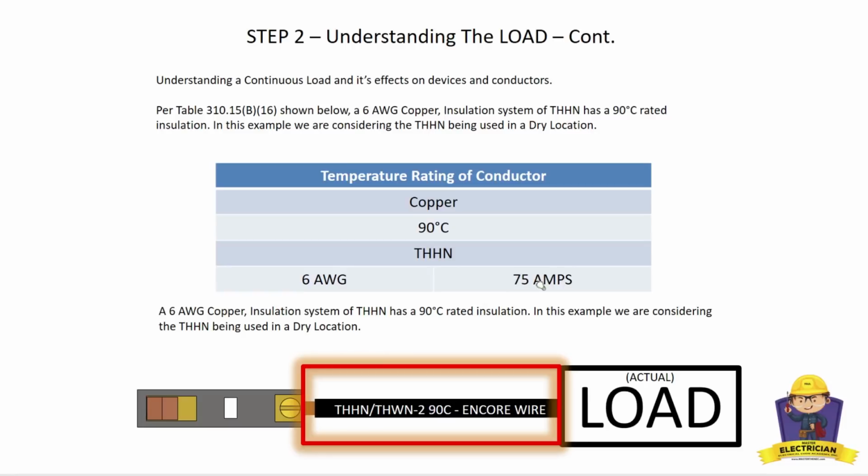Okay. Now, remembering we can't use a 90 for anything but adjustment and corrections unless all the lugs associated with the assembly are rated for 90, which you might have some lugs that stand by themselves that are not connected to a breaker that might be rated 90. If that's the case, you can use the 90 degree ampacity value. But in most cases, we're limited by circuit breakers or pieces of equipment that get evaluated, and they're going to limit the lugs to 60/75. Might not even have 60 anymore. Most of them might be just 75.